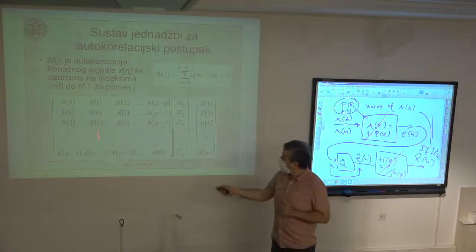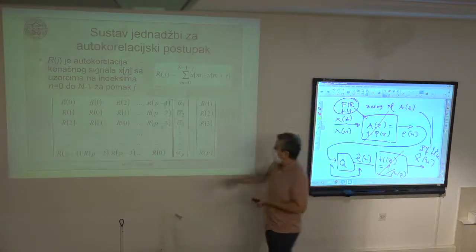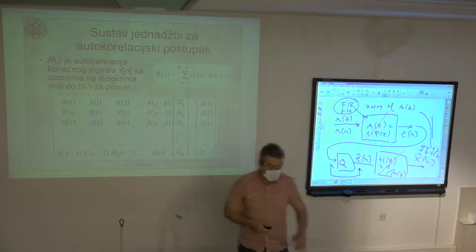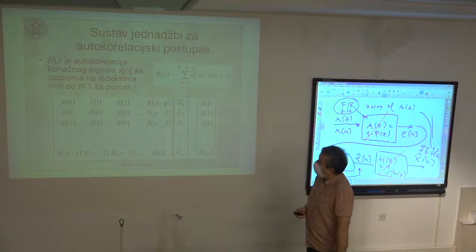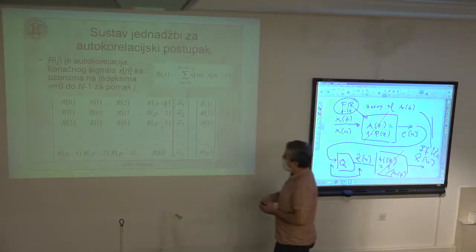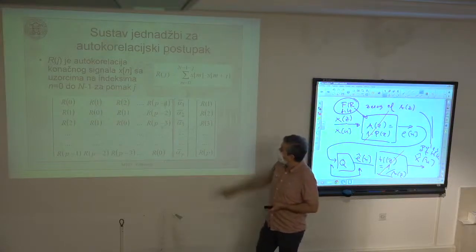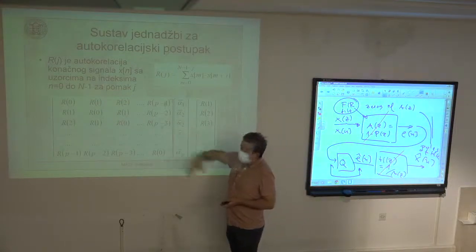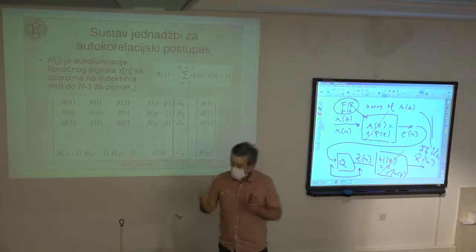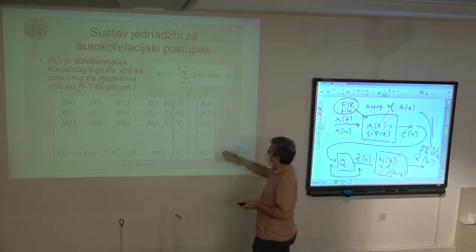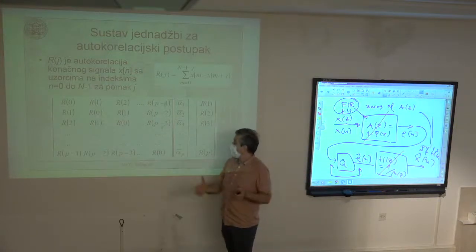So this 10 by 10 linear system of equations is solved, either 50 times per second or 100 times per second, while you are speaking. So as you are uttering these vowels or consonants, so phonemes, the mobile phone is taking the segments of this speech signal and computing optimal predictor values for each such segment.